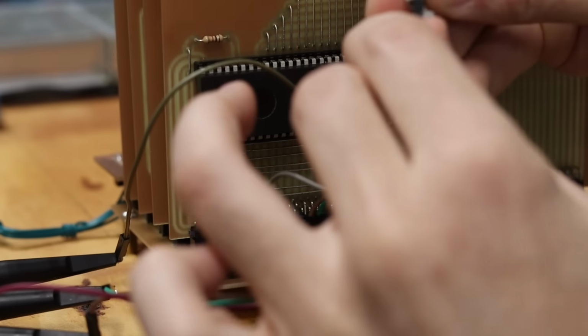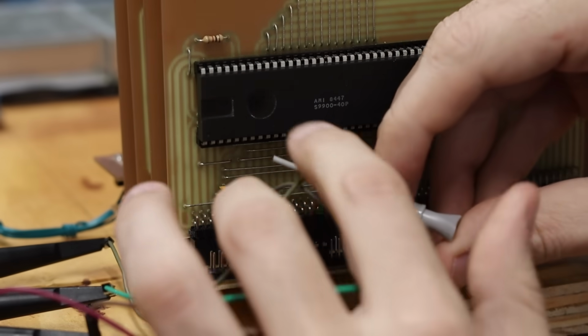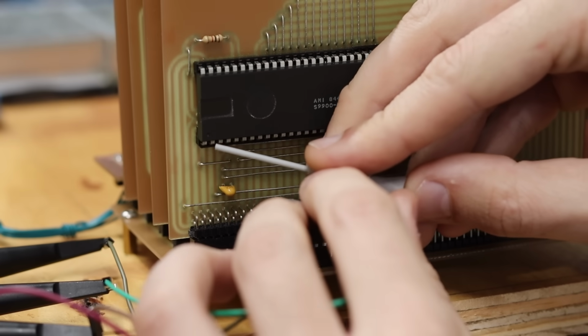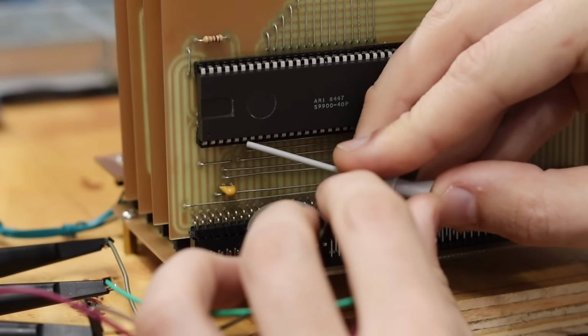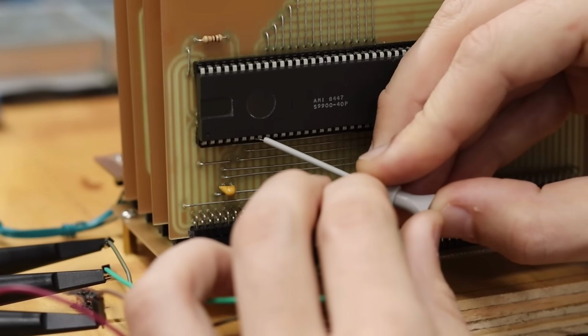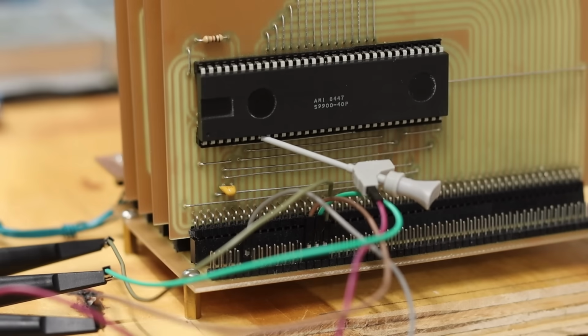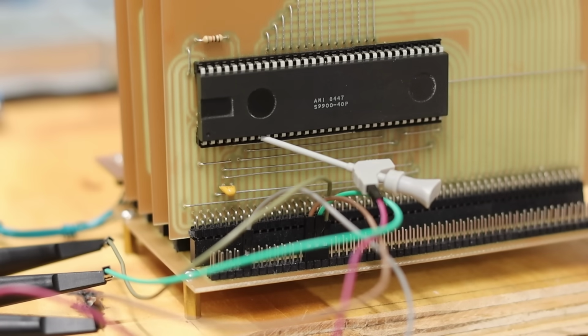So we're just going to unplug it from there. I'm going to plug in this little connector here, and we're going to go to pin 8 of the CPU. So 1, 2, 3, 4, 5, 6, 7, 8. Right there, that should be Phi 1. So now we're hoping to actually trigger off of that and see that on the scope.